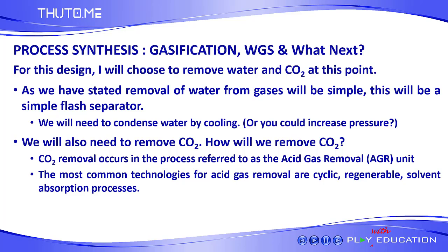As we have stated, the removal of water from gases will be simple. It will be a simple flash separator. We will need to condense the water by cooling. That's not too complicated. Or you could choose to increase the pressure, because higher pressure also will condense the water, but I think cooling will be a better option. We will also need to remove the CO2. How will we remove the CO2?